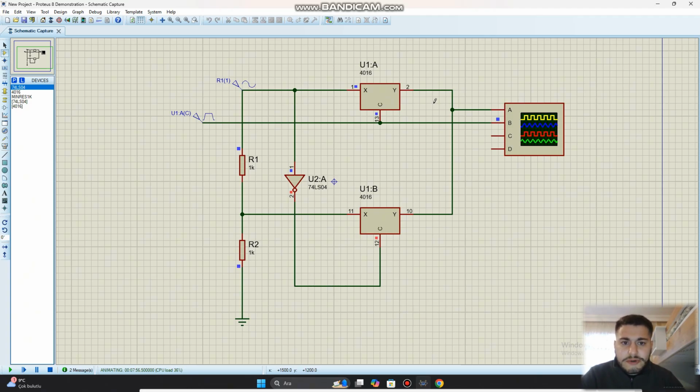When we examine the circuit operating principle, the input signal or digital data controls the switch in the 4016 chip. When the input is 1, one switch is activated and the carrier signal passes directly to the output. When the input signal is 0, a different switch is activated and the carrier signal is attenuated or cut off completely. The active switch changes the amplitude of the carrier signal, thus at the output a different amplitude signal corresponding to the bits in the input signal is obtained.